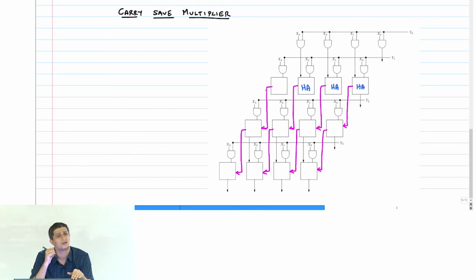What about the last one? Just one, and actually I can even bypass that, go and add it to the next bit. I can bring this guy sort of here. I will not do it for now. Okay, I'll keep this as a half adder for now. You will see the reason why. So I'm going to call it a half adder and ground the other input.